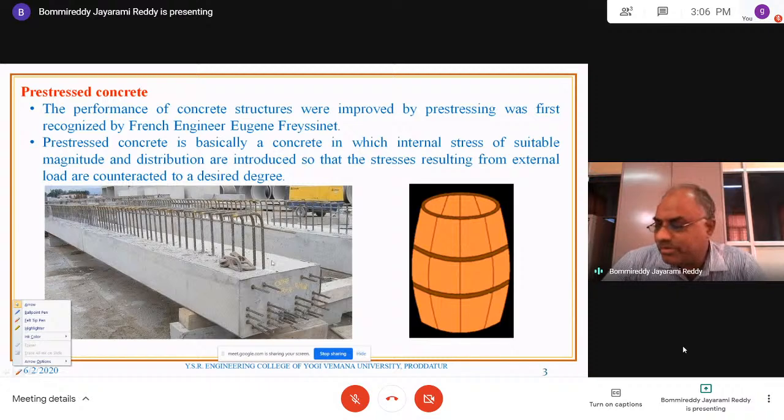So here you can look at the pre-stressed concrete normal beam. Here all these are the steel reinforcement, used as pre-stressing steel. The main purpose of it is not for resisting the tensile stresses. It will be useful for introducing the pre-stress in the member.